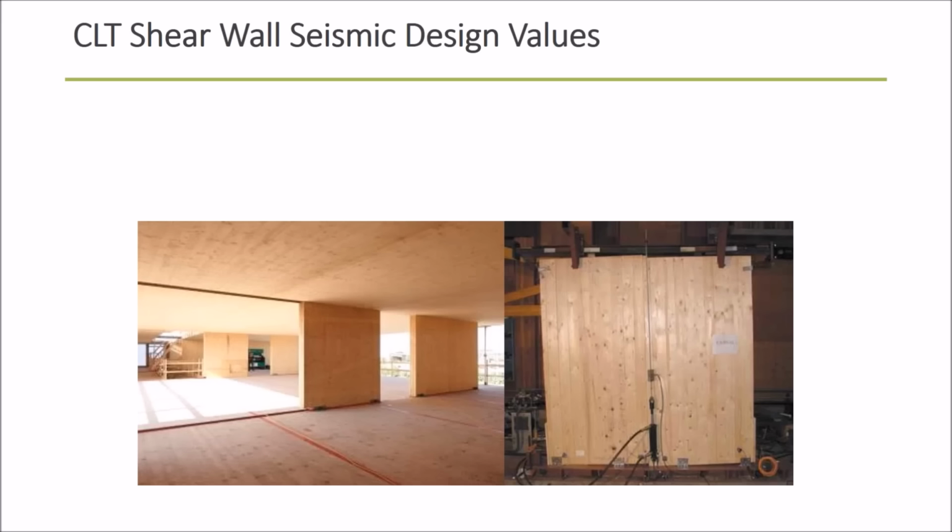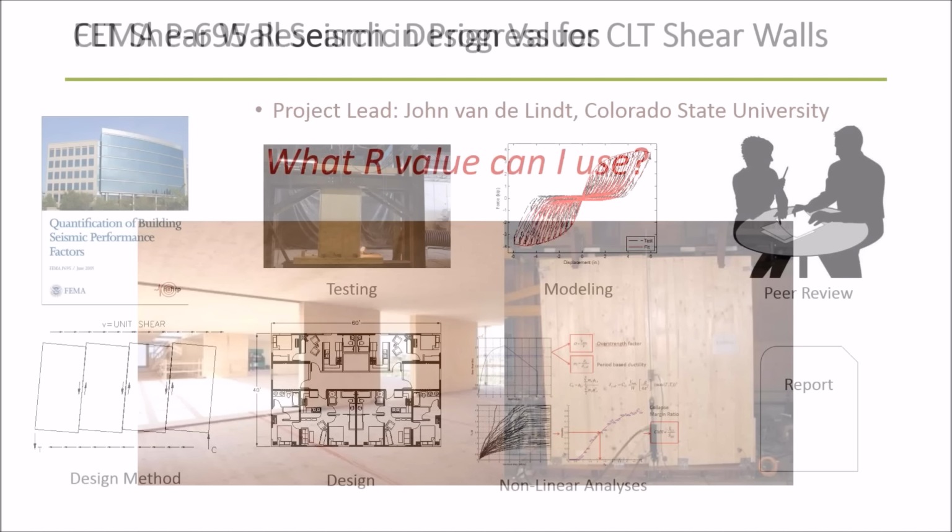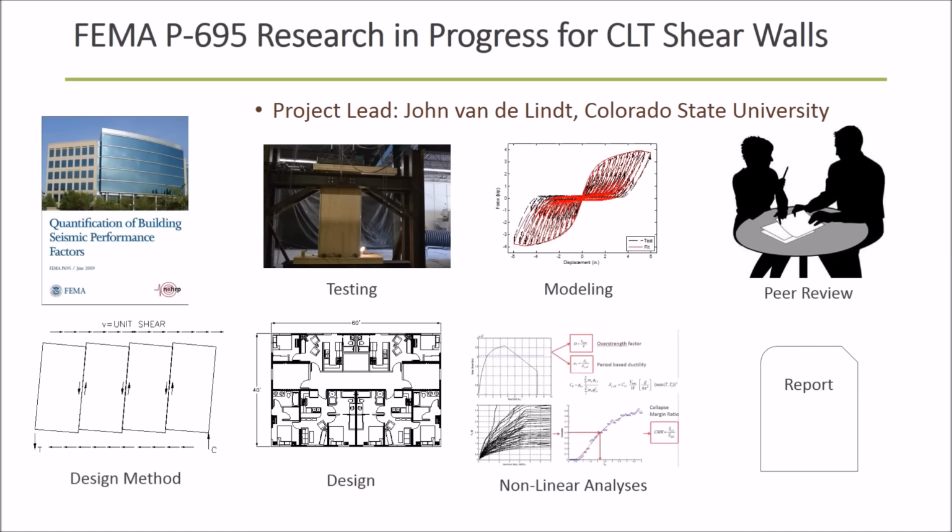That said, there are definitely designs and projects using CLT shear walls even in seismic locations. But of course, the question always regarding seismic design with CLT shear walls is, what's the R value I can use? So in reality, that's research in progress. If you track the seismic design standards over the past 10 years, the seismic and structural engineering community has really elevated the process to validate new shear wall systems, new vertical seismic force resisting systems, and that's all contained in the standard, FEMA P695.